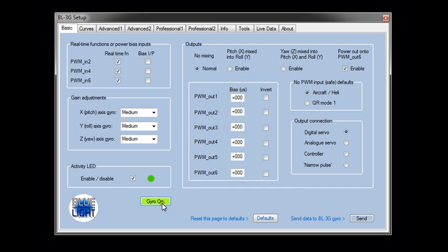By the way, the gyro can be switched off here with this big button, and then the gyro functions themselves will not operate, but the module will operate only as a mix doing the mix functions. So it can be used, for example, on a flying wing application, or with an aeroplane that has maybe 2 servos for the wings. It can be used simply to drive the correct servos with no gyro function.